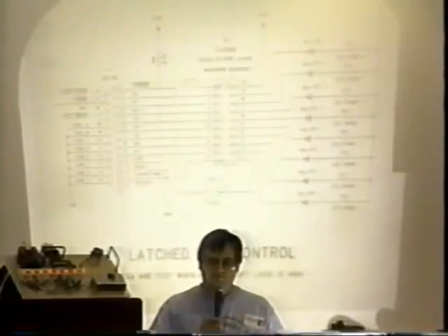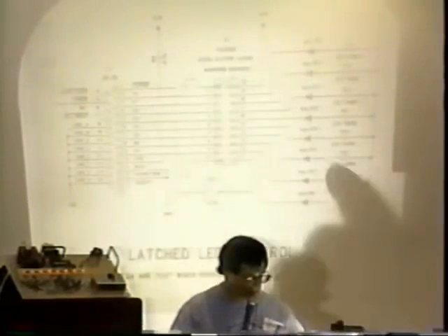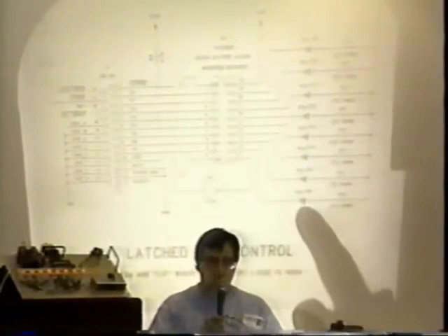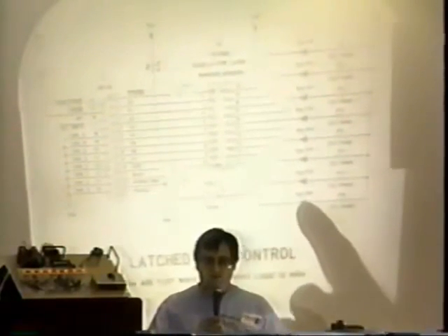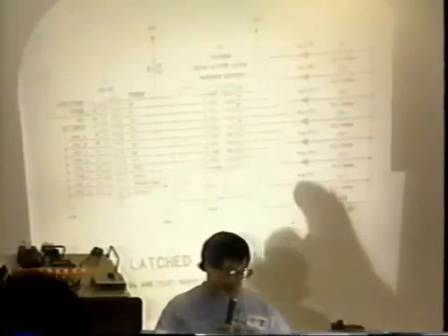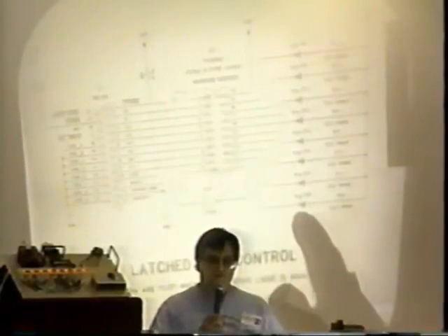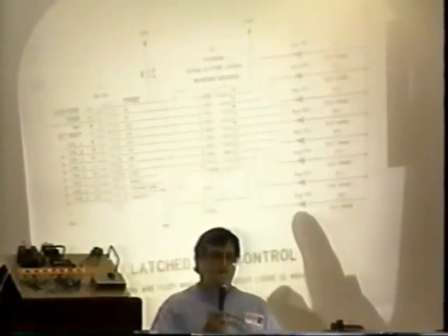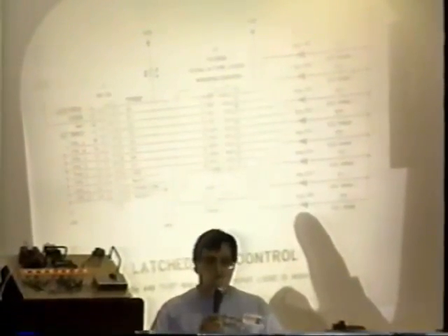Well, let's see. If I send numbers out here, I can light them up. So if I send the number 1, the first LED will light up. If I send the number 2, the second one will light up. And if I send a 3, both of them will light up. How come both of them will light up with 3? It's binary. We're sending binary.